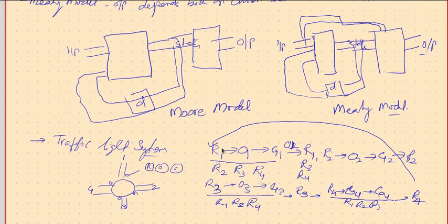In place of saying just one R1, you continuously say four times R1, one time O1, then two times G1. Then the time used for orange, red, and green will be different. So the time for red is four times the time for orange, and the time for green is two times the time for orange. So that way it becomes more realistic.